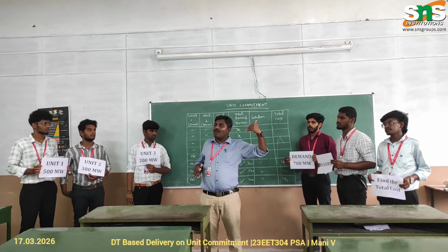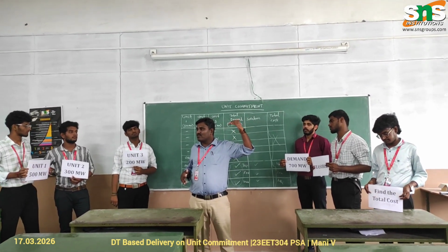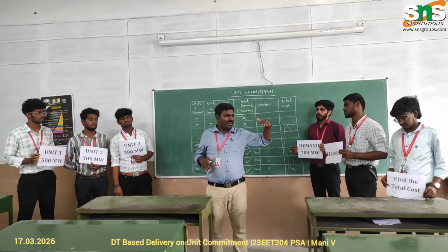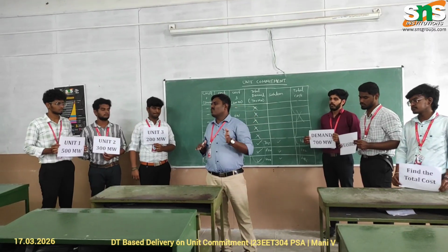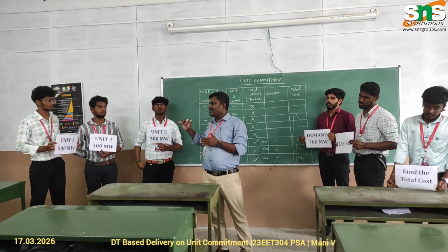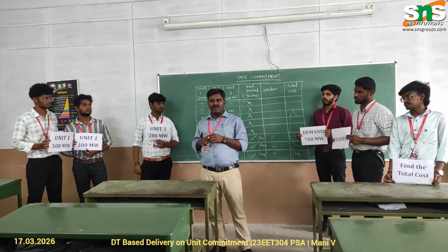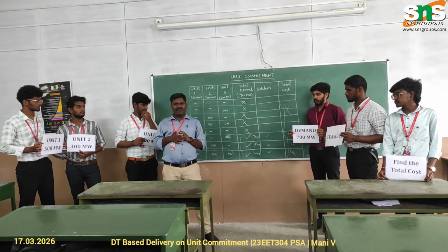Hydroelectric or pumped storage hydroelectric power plants can be used for peak hours in the morning time or evening time. For the rest of the time, we can keep the thermal power plant as base load. So this is called unit commitment.